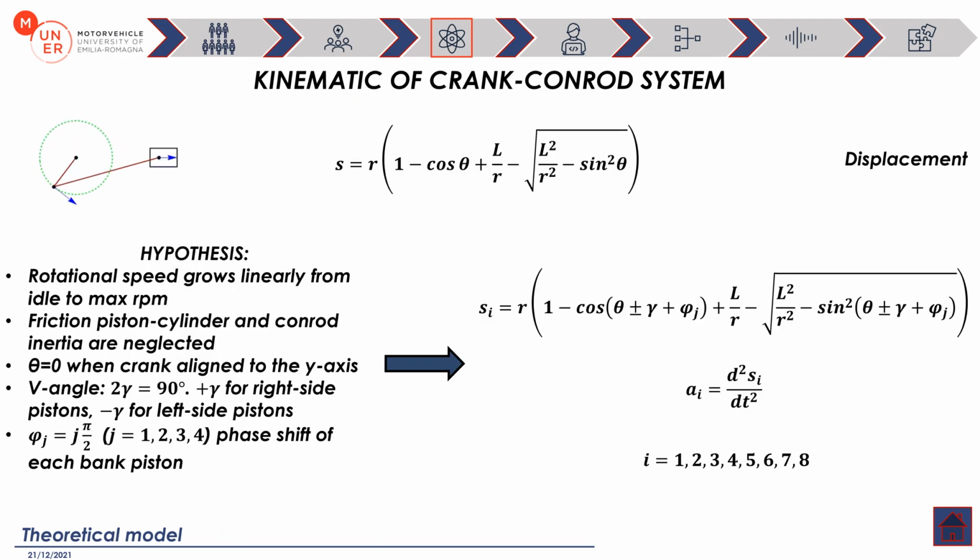The development of the theoretical model for the forcing starts from the kinematics of the crank-conrod system. After deriving the expressions for the displacement of the piston as a function of time, by making appropriate hypotheses, it is possible to generalize this formula for all the 8 pistons. Eventually, we used this expression in MATLAB and derived it twice to obtain the accelerations of